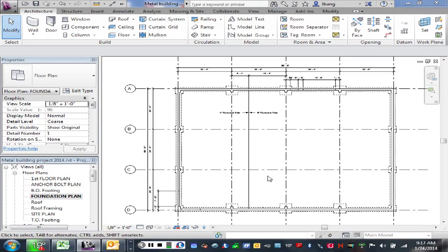Okay, so we're going to start our floor slabs for this building. And we have a 4-inch floor slab under the office end of the building and a 6-inch floor slab under the shop warehouse type end of the building, because in the shop warehouse end you could have forklifts in there, you could have heavier trucks in there and so forth that would crack up a thinner slab. So that's why we're thickening it in the shop end of the building.